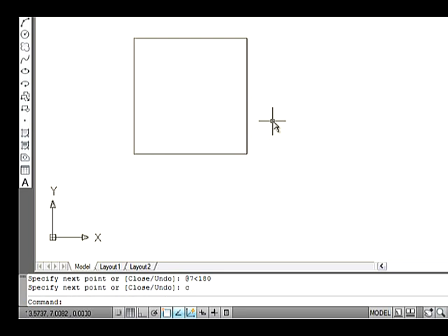Note, with relative polar coordinates, you should always enter positive values. Most users find that relative polar coordinates are the most logical method to coordinate entries in AutoCAD. You don't need to calculate displacements in the x and y directions, and distances are actual distances.